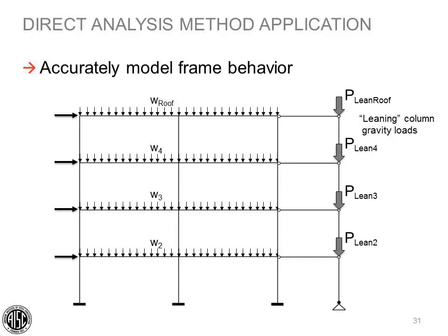The columns on the right here are what I've referred to as the leaning columns. They're the columns that represent all the other gravity columns that are stabilized by the frame we're analyzing. As the frame deflects, these columns lean on the lateral system for support, and these gravity columns deflect also and add to the overall P big delta effect. The P big delta effect from these leaning columns works to destabilize the frame, so they must be included in our analysis. All loads or conditions that work to destabilize the structural system should be accurately included in the structural model.